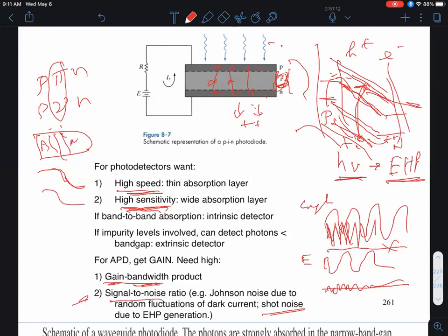will have, the holes come out at this end and the electrons at the other end, a statistical fluctuation. Now, if the numbers of those electrons and holes are large, that statistical fluctuation on a fractional basis, of course, is going to be small. But in these photodiodes, they're typically sensing very, very low light intensities in many cases. And under those conditions, this random electrical noise, because of the discrete nature of the electrons and holes, gives rise to what's called shot noise, okay?